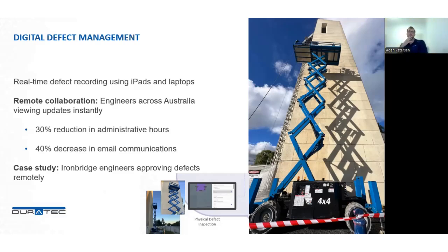Digital defect management. This kind of system revolutionized how we handled complex restoration. Our teams would go on site using iPads and laptops to record defects in real time directly into the 3D model. You can see a screenshot in the middle of the screen there. That's the screen capture of the iPad screen. As they identified it when they were on the mast climber or cherry picker, they were able to snap a photo and input those details.